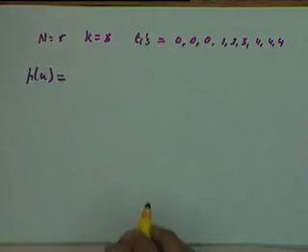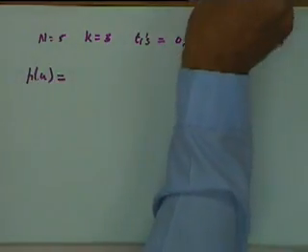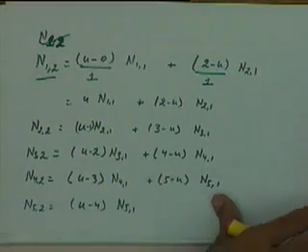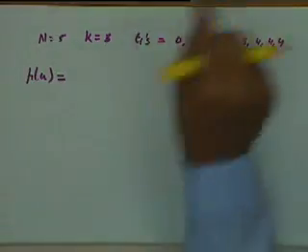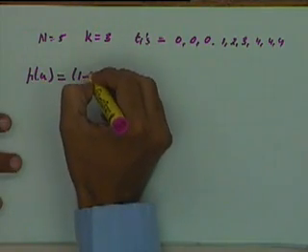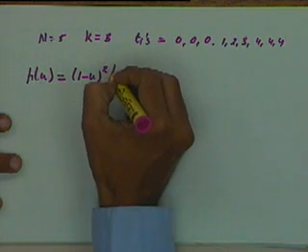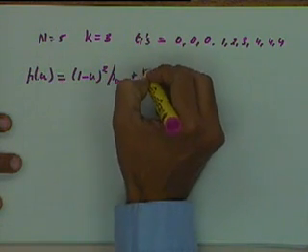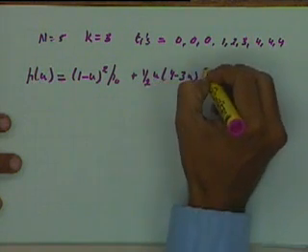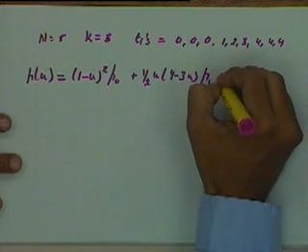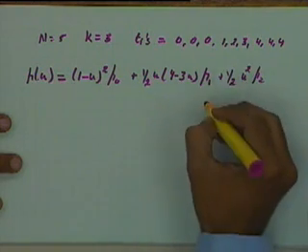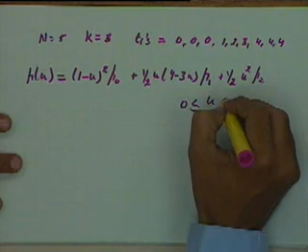If I find out all these expressions the way I did for N12, now I will have to find N13 and so on. Okay. So I will get my definition of the curve P(u), that will come out to be, I am writing the expression directly now, (1 minus u) whole square times P0 plus half of u times (4 minus 3u) times P1 plus half of u square times P2, and this is in the range when u is between 0 and 1.